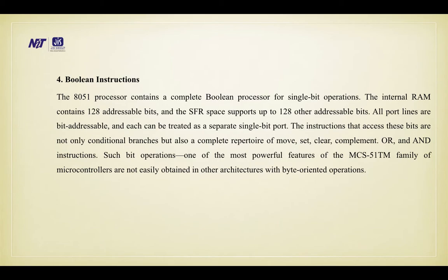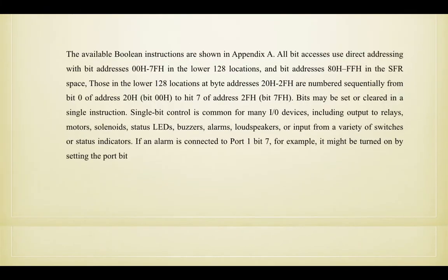The instructions that access these bits are not only conditional branches but also a complete repertoire of move, set, clear, complement, or AND instructions. Such bit operation is one of the most powerful features of 8051 family microcontrollers. This is not easily obtained in other architectures with byte-oriented operations.